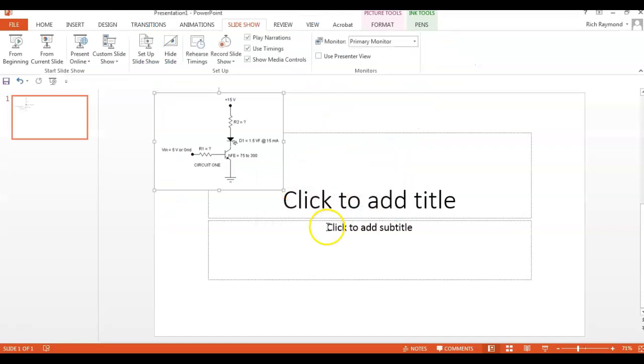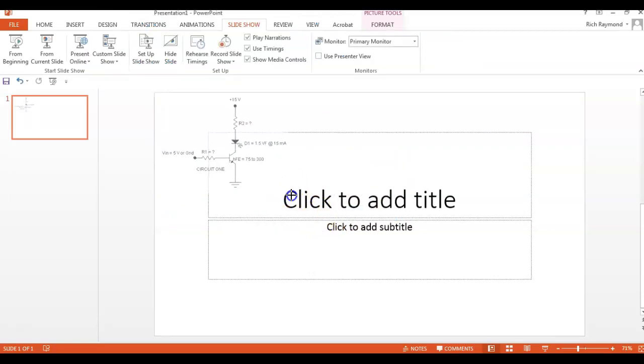What do you mean, for the diode? Yeah, that would be the actual data sheet value. It's somewhere between like 1.5 to 3.8, right around in there. So if you don't have the data sheet, 2 is a good number. Rule of thumb. Yeah, approximately 2. We wouldn't say 2, we'd say approximately 2. And that's the way it would be on a test.